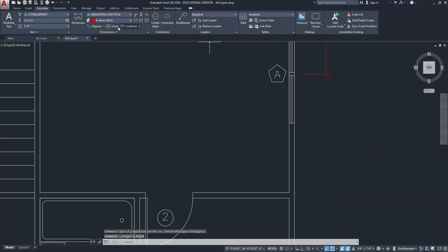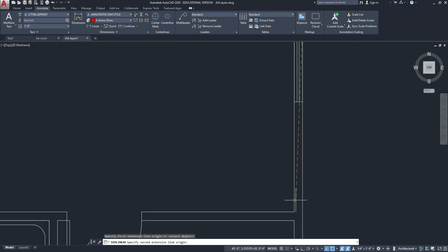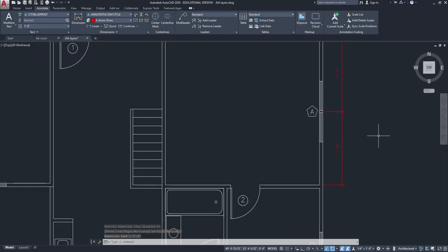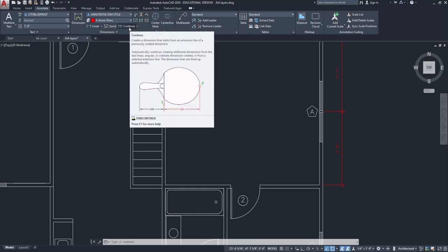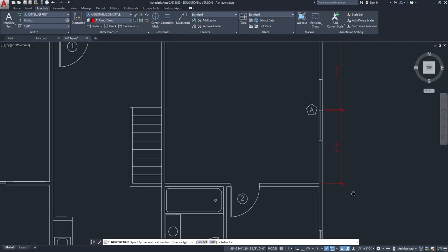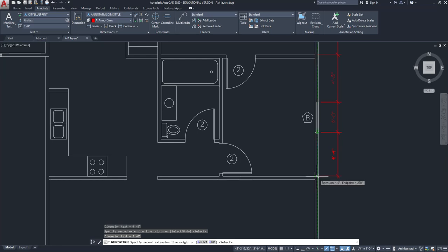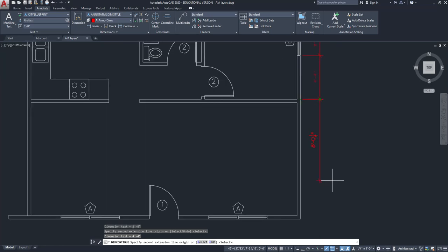Delete. I could click here on linear, click, not straight line, click, come over here to the dimension by it, click again, and those line up, okay? So I could hit enter and I could continue on with this dimension string, but I could also come up here to my dimension tool palette, and you see we have a continue option right here, okay? I can click on dimension continue, and AutoCAD just picks up and lets me continue. It just makes this a continuous command, okay?